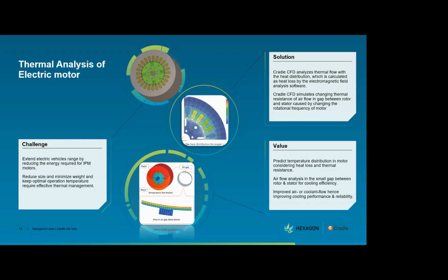As we can see, all these aspects are strongly connected to each other, since downsizing the motors will require very effective thermal management. Cradle CFD is able to accurately predict the heat distribution inside the e-motor, as well as the thermal resistance of the air gap flow according to the rotational speed. And those analyses will be helpful to improve cooling efficiency.